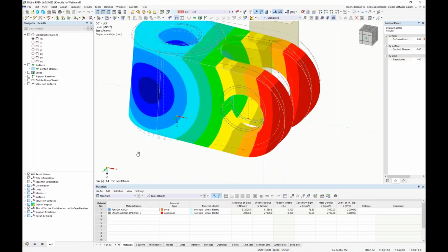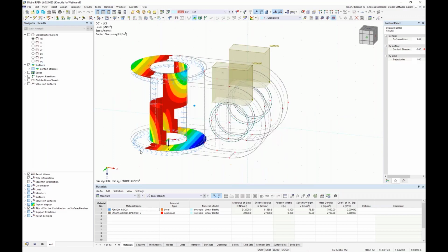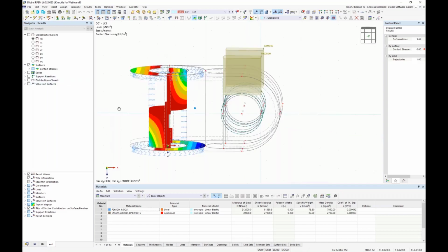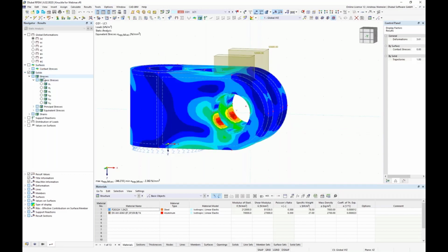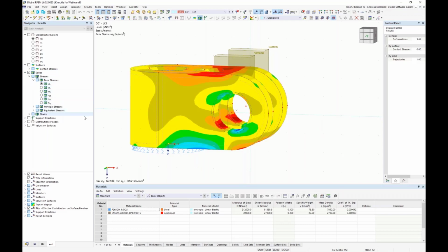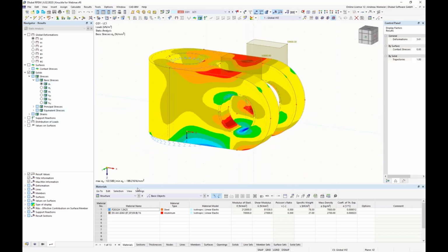What is clear? Yeah. And for checking loading boundary conditions, you will see you get the restrainment for the top surfaces, pressure here, and in the inside, in the bearing, you get also pressure vice versa, transporting a bending moment. So far, it's reacting fine, and it will give you, let's say, stresses in X, in Y, and Z directions. You get extreme stresses, what is interesting for design, and you get also here strains.